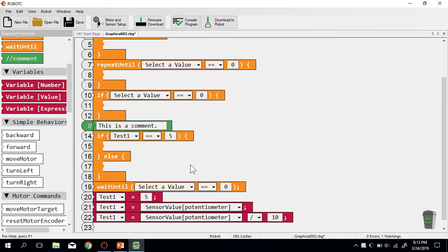So you can convert the potentiometer to its degree. If you were to grab a calculator, 5,000 divided by 180 means you'd have about 28 values for your potentiometer reading per degree. So this would convert it from its raw data into degrees. That's where something like the equation would be useful.